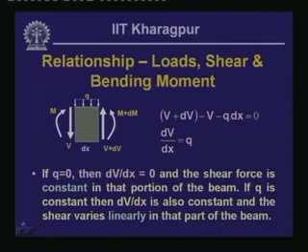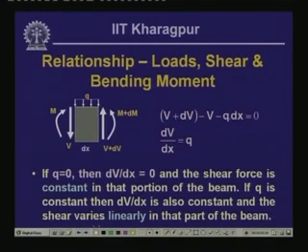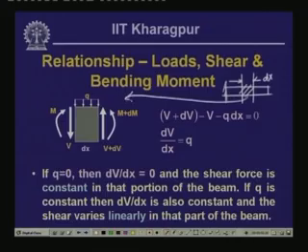Now, to do that, let us look into some of the aspects of how different kinds of loads can be related with the stress resultant quantities, which are nothing but the shear force and the bending moment. Now, if we consider a small segment of the beam, let us say that we have a beam over here which is supported at this particular end, and we would like to take a small segment out of it which is of length dx. So, this particular segment is drawn over here.